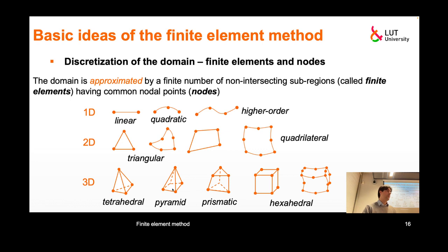And actually, when you are mixing different types of elements in your domain, and in the real engineering world it's a pretty common situation that you are unable to divide your domain into only hexahedral elements, for instance, because it has a complicated shape and you don't have a good enough algorithm to fit hexahedral elements into it, to approximate it entirely with hexahedral elements only. But you still might want to use them in some parts because they have certain advantages in comparison to tetrahedral elements.